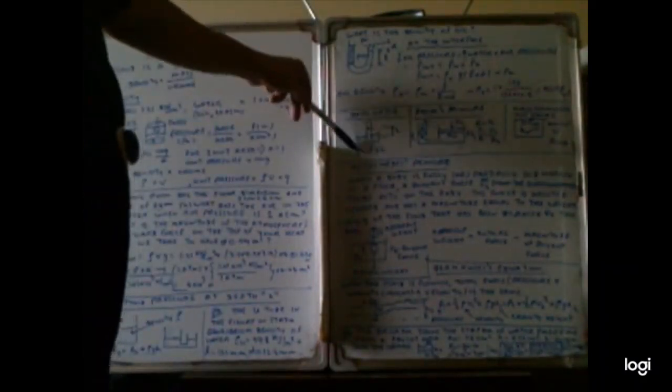With the barometer we can measure the air pressure. Air pressure is rho multiplied by g multiplied by h, where rho is the density, g is the gravity, and h is the height. And Pascal's principle: this is for the two cylinders here. F1 is put on the area A1, F2 on the area A2. So pressure P1 equals pressure P2. Therefore, F1 by A1 equals F2 by A2. And the fluid moves in equal amounts.